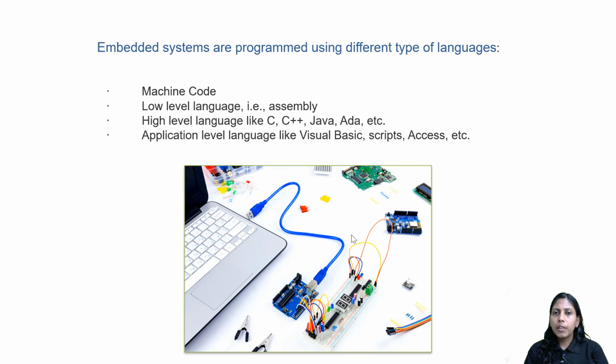And Java, of course, you can use. The problem with Java, again, is the code size will be more, so the complexity will be more. Earlier, we used Java programs in smartphones and so on. But for the JVM, the space it consumes and the resources we need are more. So that's the reason we are not using Java much for embedded programming.